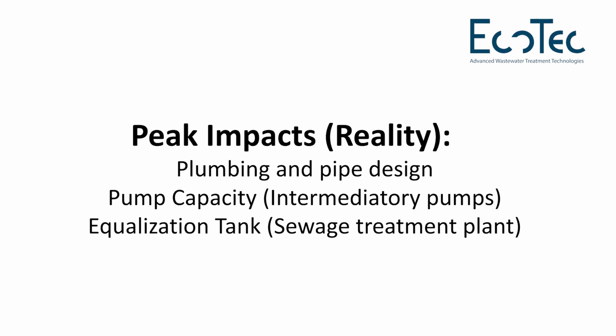Finally, where it affects the sewage treatment plant is in the sizing of the collection or the equalization tank. So, you see, the influence in the sewage treatment plant is only in the equalization tank, whereas the peak has its influence on the sizing of the pipes and also in the sizing of the pumps.